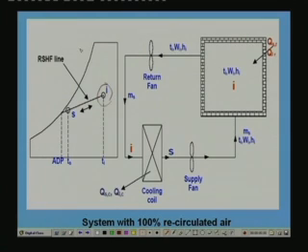We know this conditioned space state I based on the comfort criteria. This is known to us. Okay, so we can place this point on the psychrometric chart, and the slope of this line can be obtained if you know the value of RSHF. Okay, for the time being, let us say that we know the latent and sensible heat loads on the building, right? So we can calculate RSHF, and from RSHF we can find out what is the slope of the line.